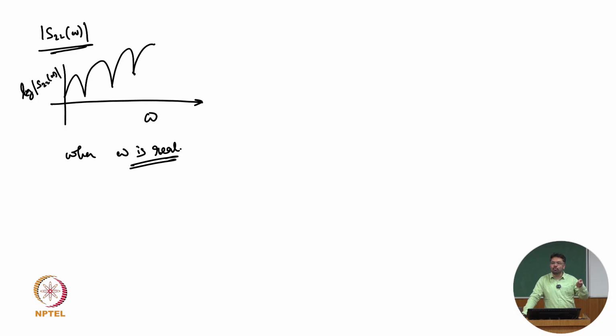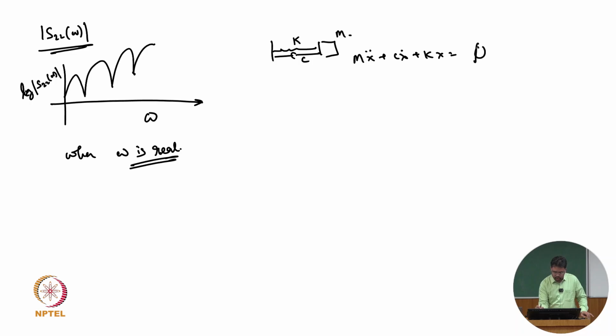We wrote it as real. If you recall, suppose we are solving this system. We don't have to take anything very difficult, just take it like this. Equation of motion equal to 0, just 0 because we are solving for the natural frequency. What is x? e to the power lambda t.